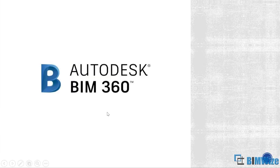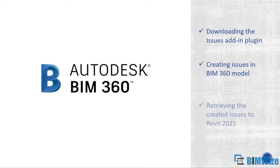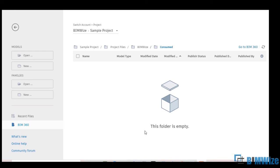In this section, we're going to discuss about downloading the issues add-in plugin and creating the issues in BIM 360 model, and finally retrieving those created issues to Revit 2021 application. So first things first, we're going to see how to download the BIM 360 issues add-on for Revit 2021. To download this plugin, you will be needing Autodesk account.